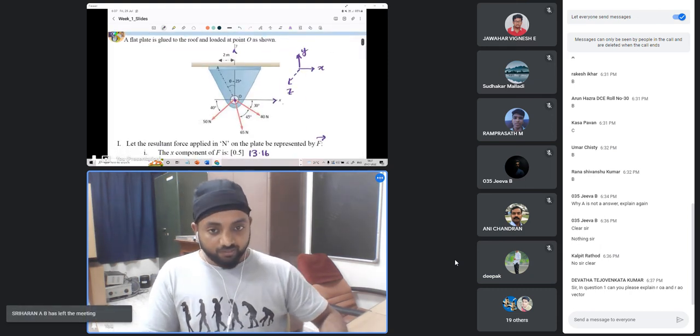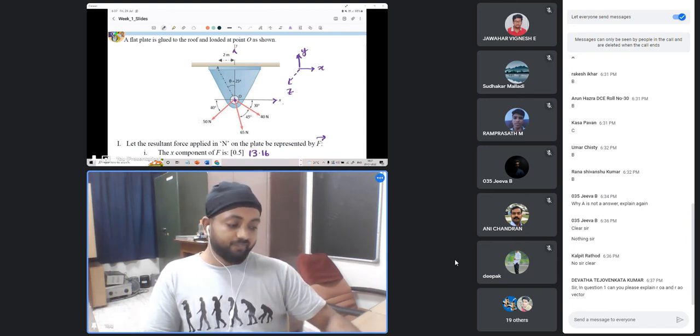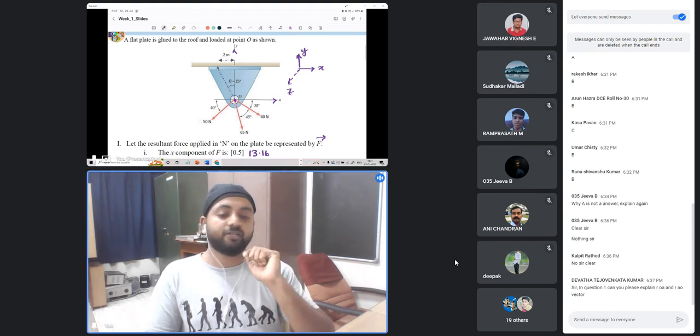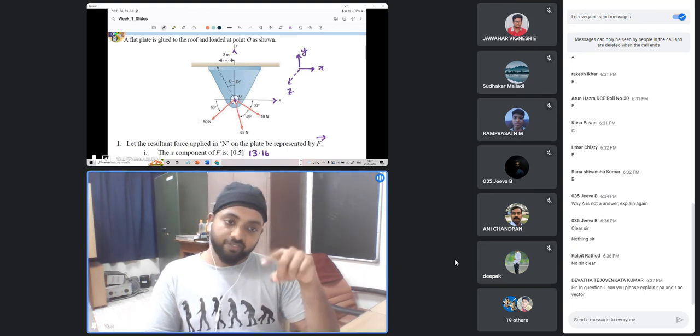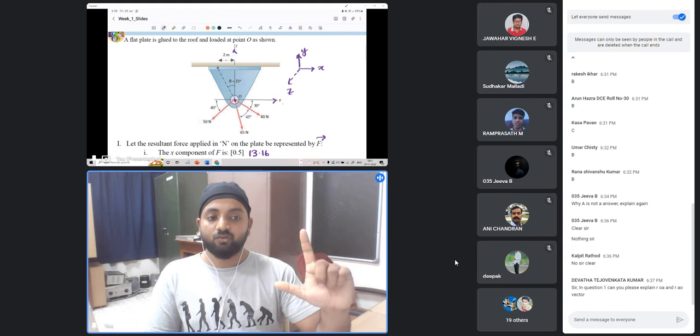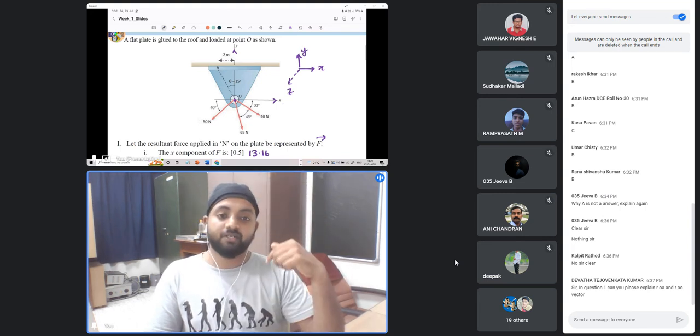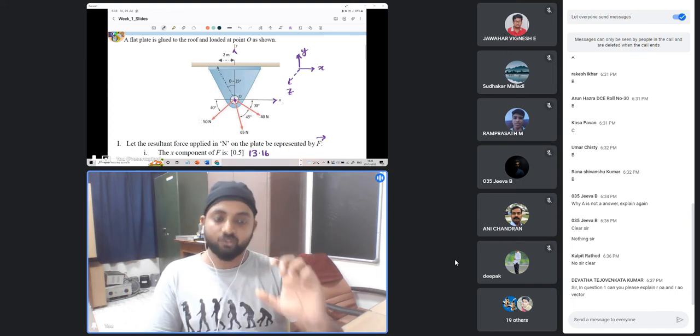You have a point A, you have a point O. Now, when we say position vector, it is always with respect to some origin. If we say R A/O, it means that we have fixed the origin at O and we are looking at A. What will be the position of A as we see it with the origin sitting at O? That is R A with respect to O.